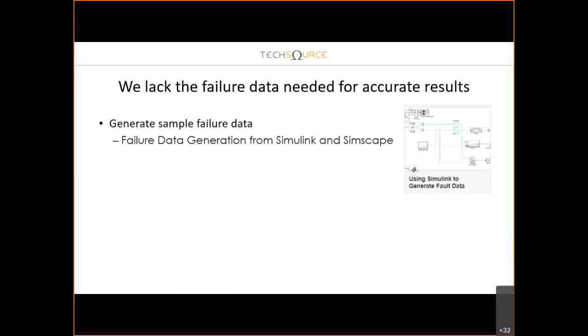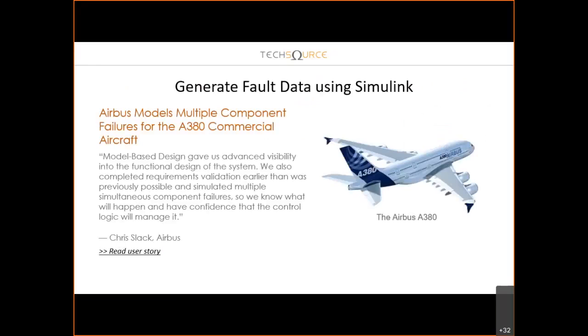So an engineer with sufficient domain knowledge can incorporate this behavior into the model in a variety of scenarios, which can simulate failure data by adjusting temperatures, flow rate, or vibration, or adding other sudden spikes. So this scenario can be simulated and then we can get failure data and label and store them for further analysis. So you can use Simulink to do that.